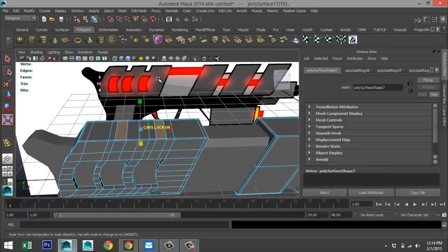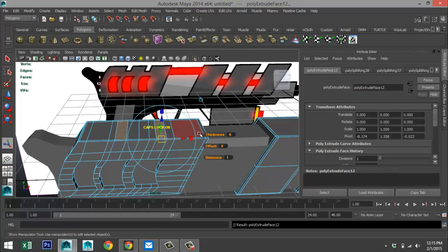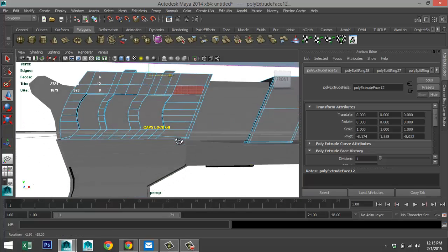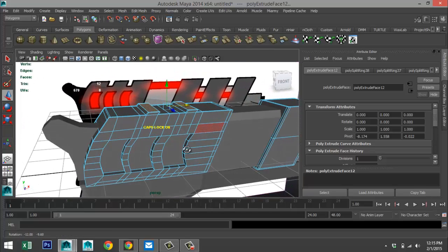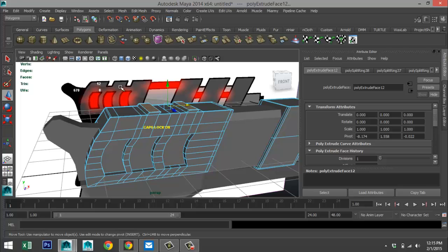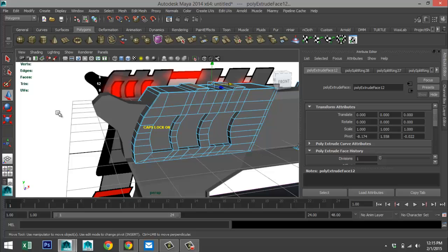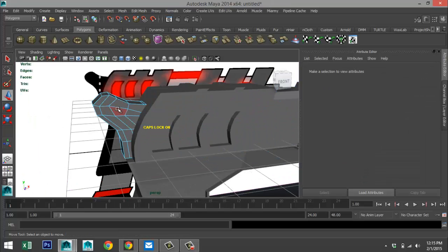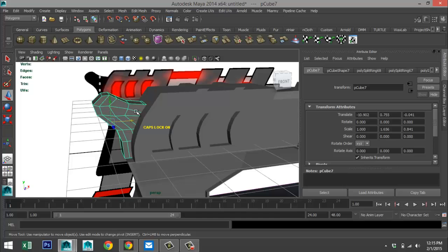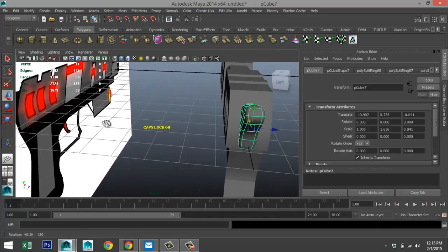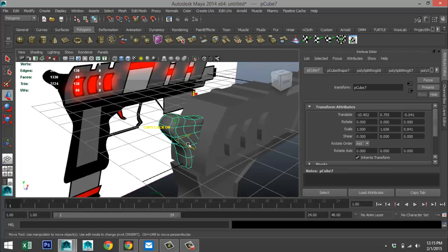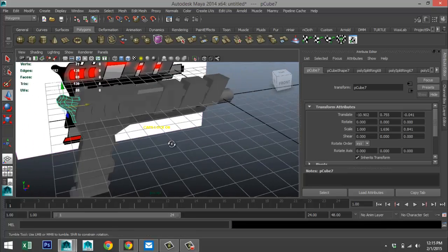And I don't necessarily want to create these gaps. I actually want to raise them a little bit. So I'm going to go to Edit Mesh, Extrude, hit W, raise them up just a little, and move them a bit forward to just create that detail. Yeah, it doesn't make sense for me to have these in here for some reason. So, okay. Just make sure if we smooth this guy that he is okay. Yeah, it's not bad. Okay, cool. There we go. So we got all that.